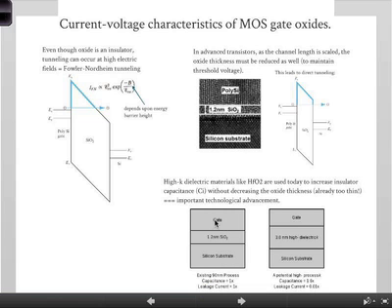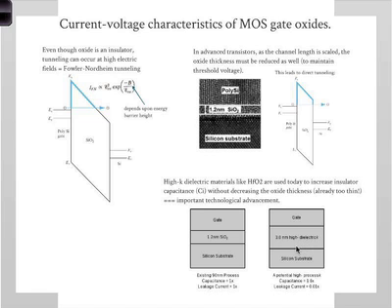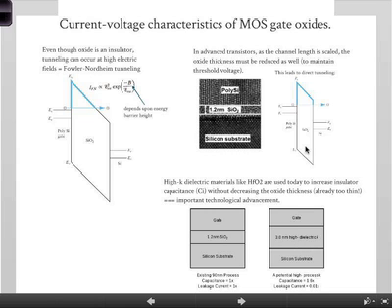But anyway, if you look at the capacitance is 1x, let's say, so relative capacitance. Leakage current is 1x. But if you replace that with hafnium oxide, which is a higher dielectric, so you can use a thicker layer, 3 nanometers, twice as thick, roughly. What happens? You can see the capacitance is now increased to 1.6x, which is a good thing, as we'll see. You want a high capacitance, a high impedance going into the small signal. At the same time, the leakage current is now 100 times lower. And the reason for that 100-time decrease is a thicker oxide. So remember, this tunneling current depends inversely, exponentially inversely on the thickness.